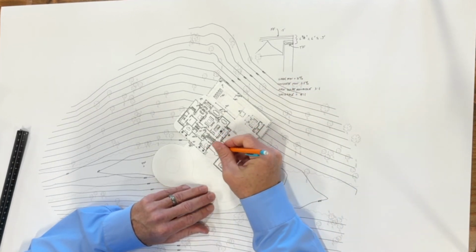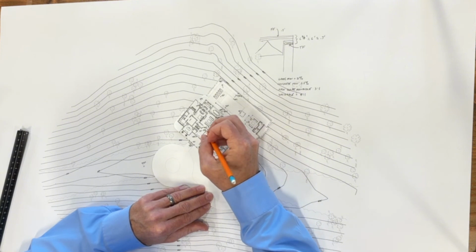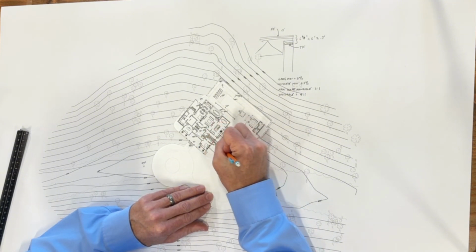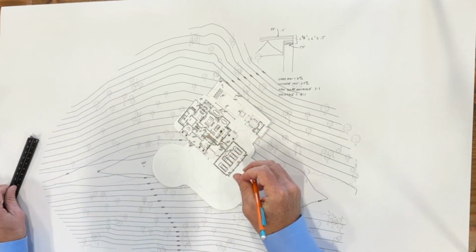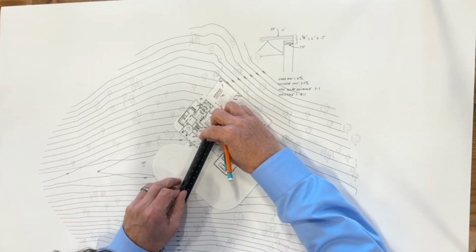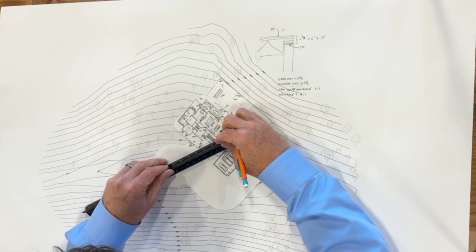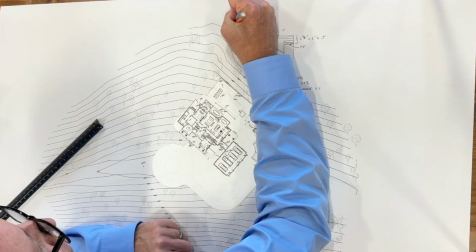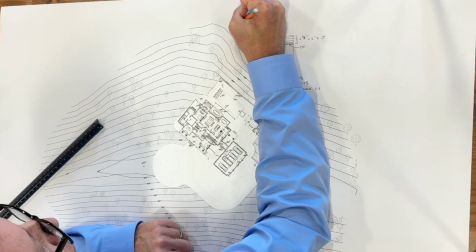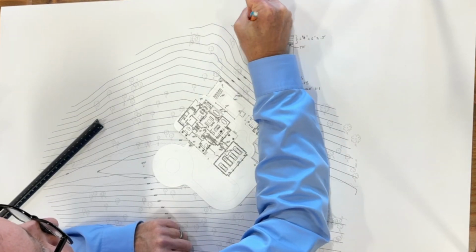So here we kind of have a grassy area, so you want that to be a 2% slope. So the water that hits this corner or this corner is going to have to drain out to this spot. And if that spot is 25 feet, let's call it 30 feet. So it's 30 feet, and slope equals rise over run.